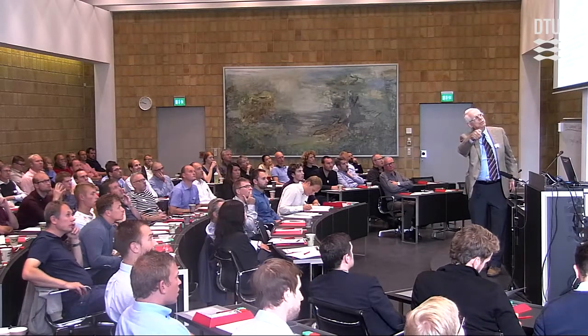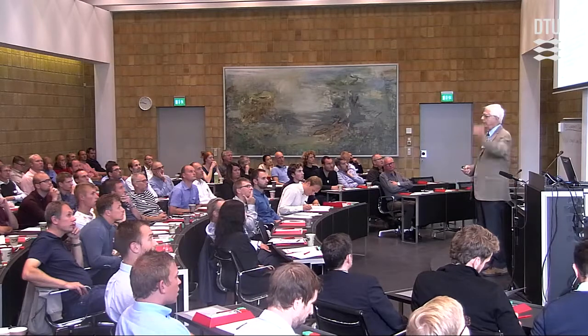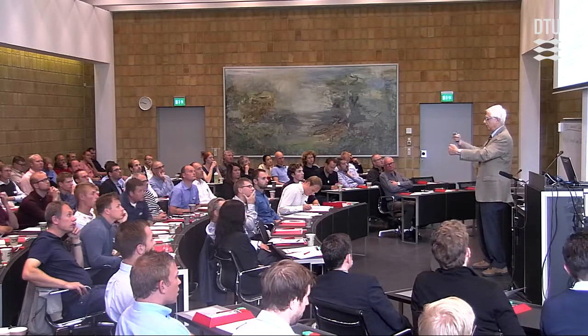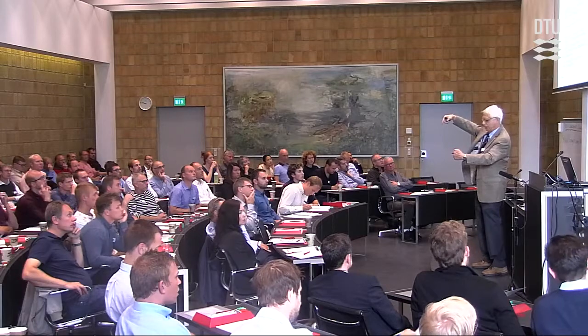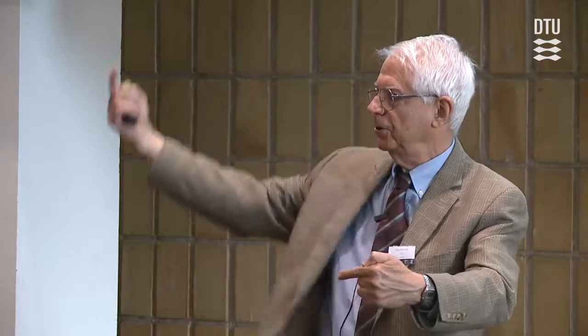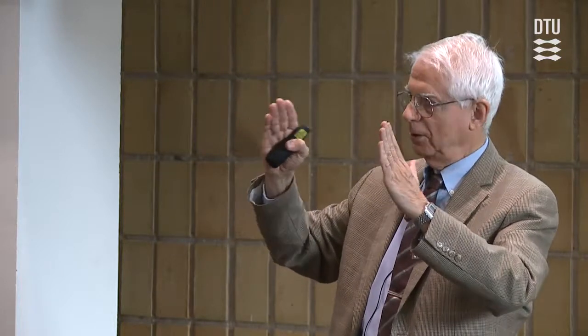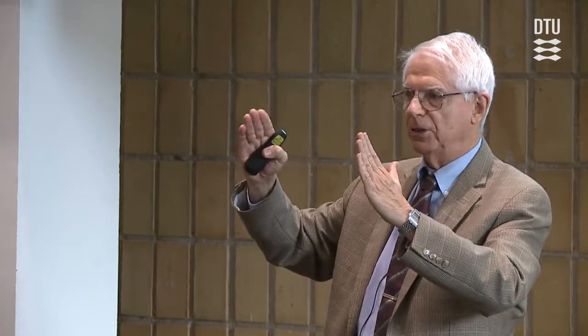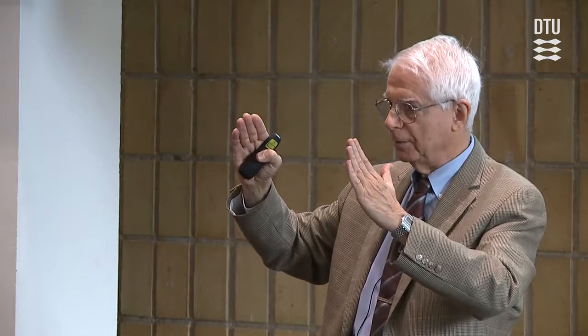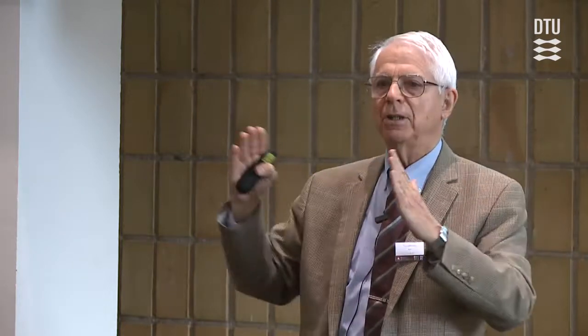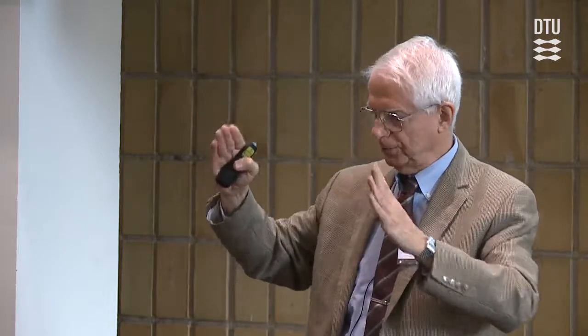Identify the dimensions inside each part that carry the chain. The chain enters the part at one locator surface and goes out of the part at some other locator surface and enters the next part. And those two locator surfaces must be located properly with respect to each other inside the part. That's what you do with GD&T or with tolerancing generally, is to locate those surfaces, because the location is going to enter the part here and leave the part there.